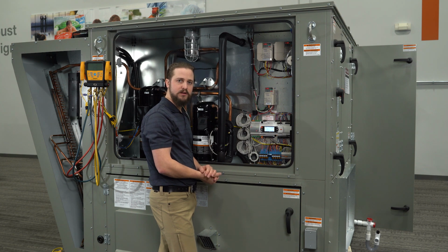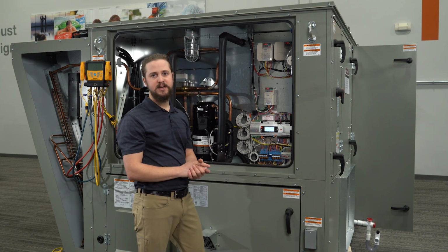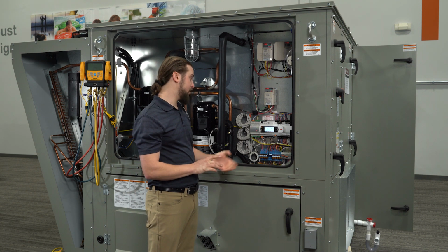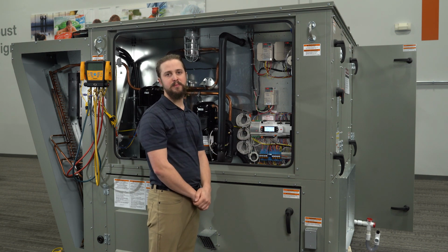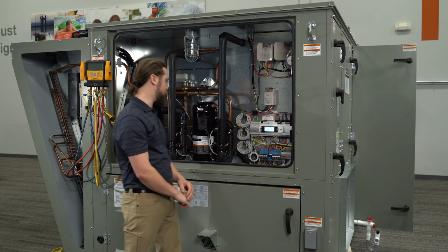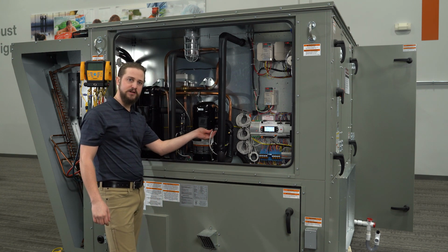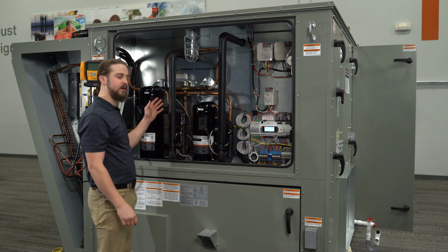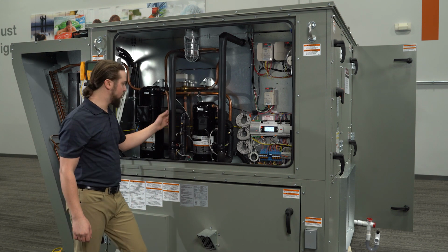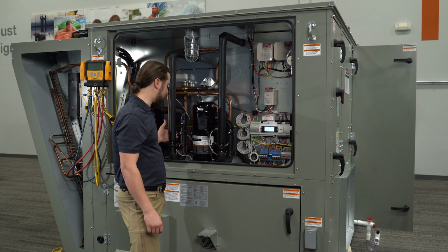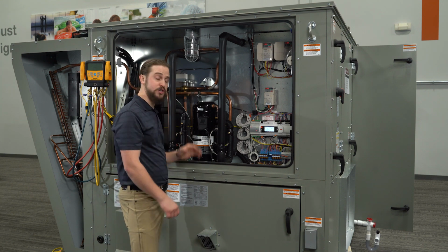Another thing that you can do to determine if there's a leak is looking at your refrigerant pressure transducers. There is a way built in to the Corel platform that you can view the refrigerant pressures transmitted with our discharge pressure transducers. And even on inverter compressor circuits, you will have a suction pressure transducer that'll be providing pressure readings.